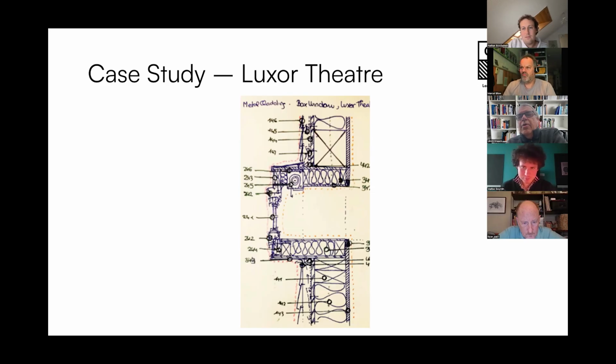Because as you've drawn it here, it's obviously again some kind of thermal bridge, because you have a part where the insulation is lost. That's a building of what, 1990s, 2000-ish. So insulation was already an issue. So I would believe that they find a solution to at least have this blind a bit smaller, so that there's maybe insulation, but some insulation left.